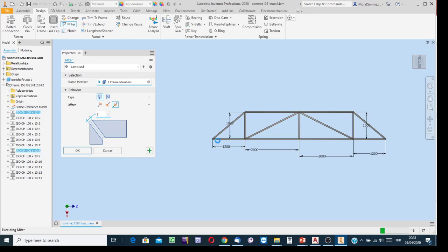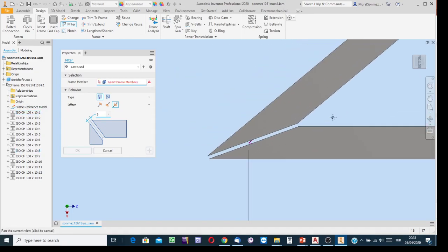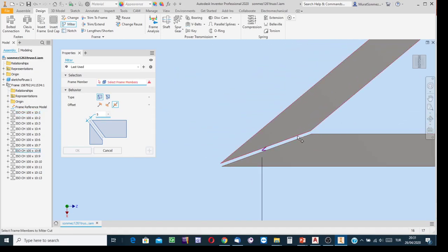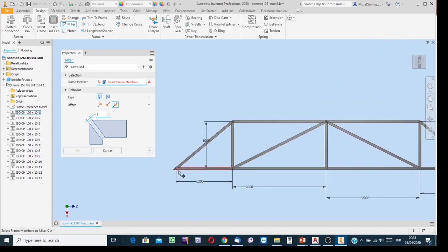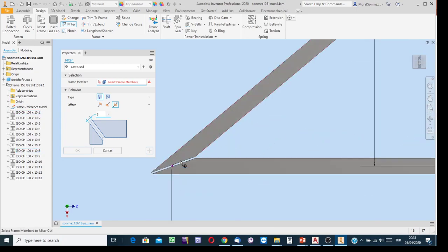After clicking on apply, zoom in. You see, here at the corner, the members are further extended, but their interface portions are deleted. And between the ends of the members, as I fixed over here, there is a 5 millimeters empty space. Yes, I solved the trouble at the joint. There is no interference.